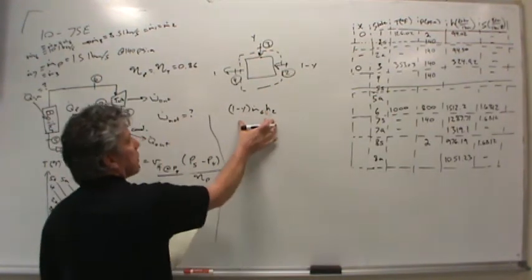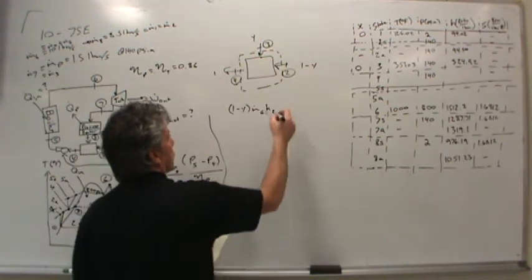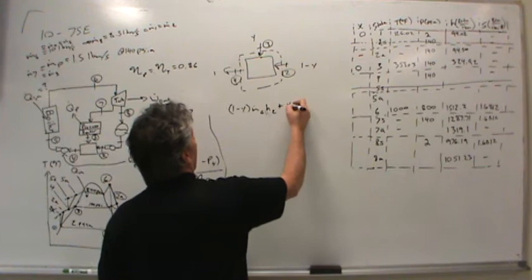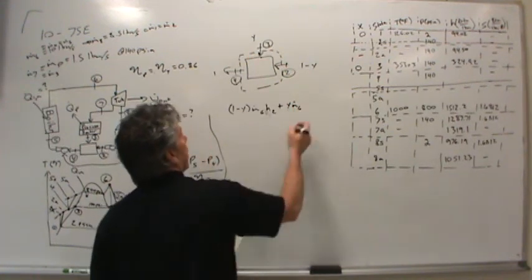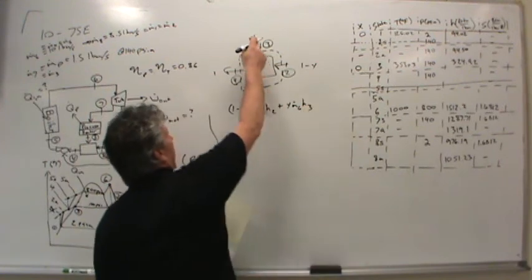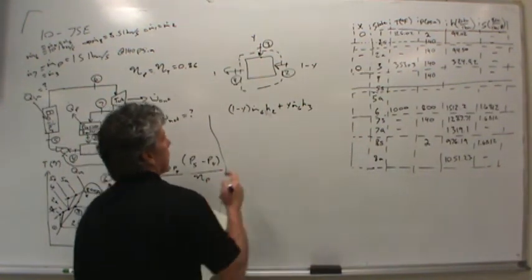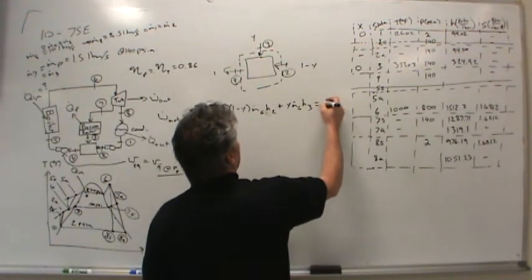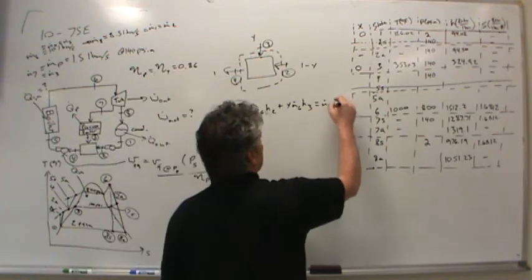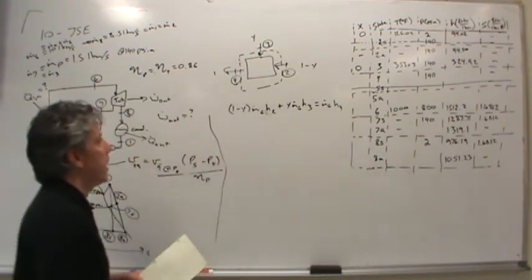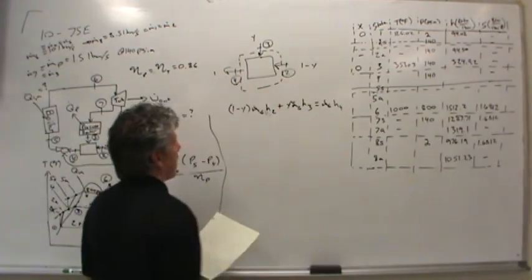Understand this quantifies the rate at which energy is carried by mass in stream 2, plus y, this fraction, of the mass flow rate through the boiler, times the enthalpy in state 3, that quantifies the energy carried in by the condensate in state 3. This is equal to the mass flow rate in state 6, 100% in other words, times the enthalpy in state 4. And again, what happens is the mass flow rate in state 6 cancels out.